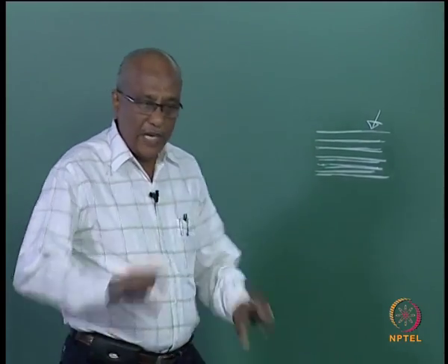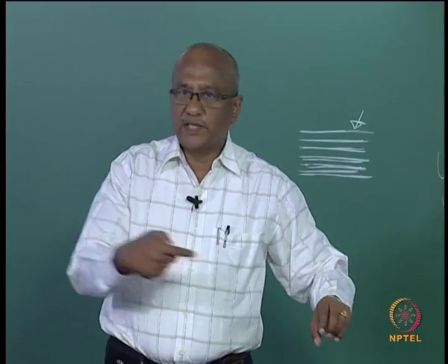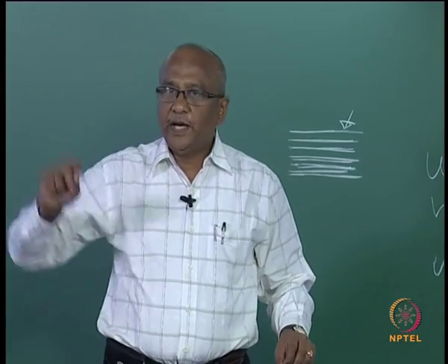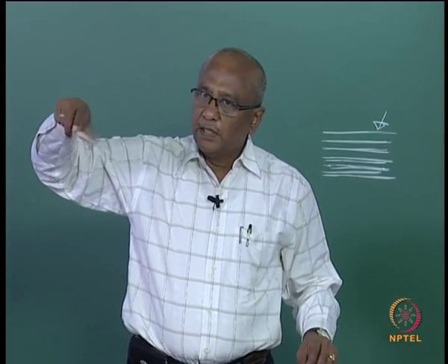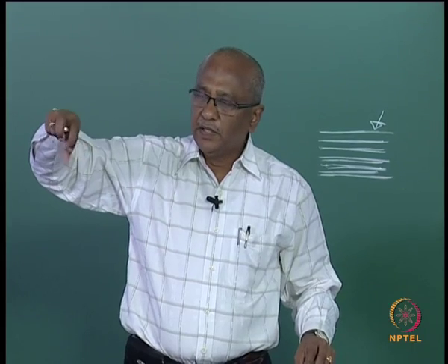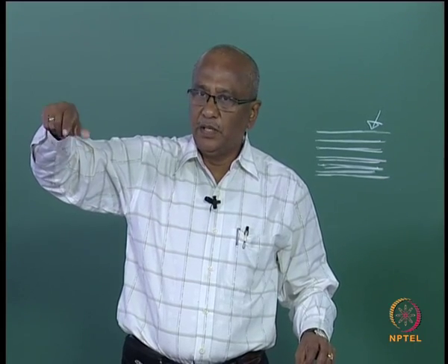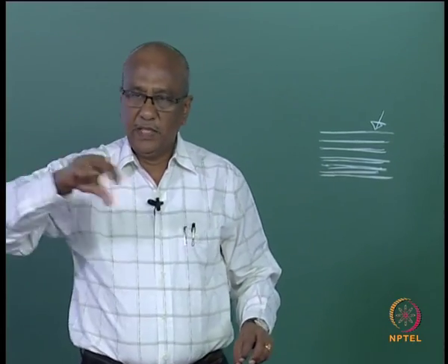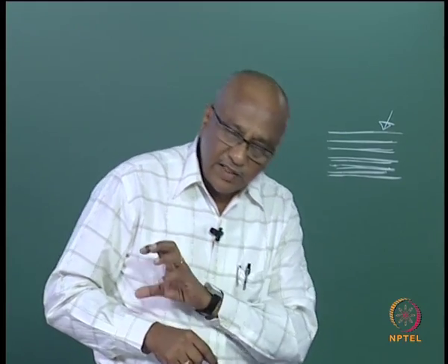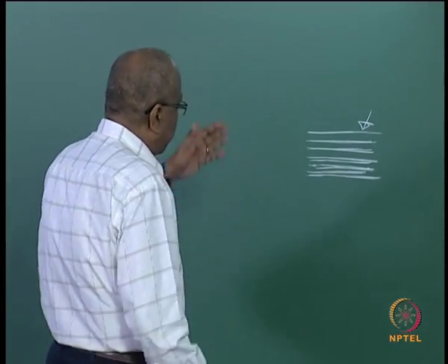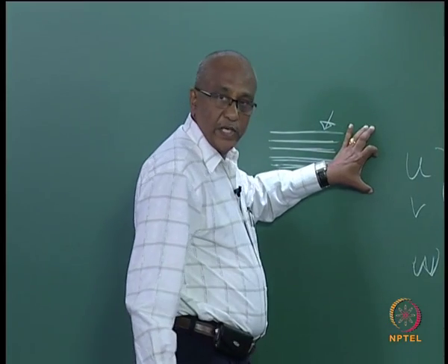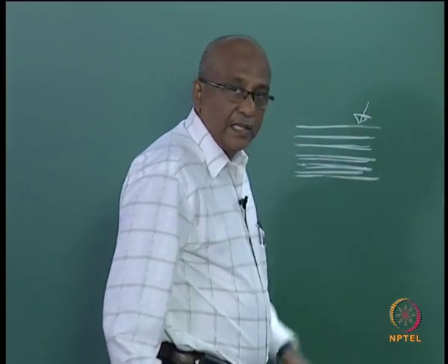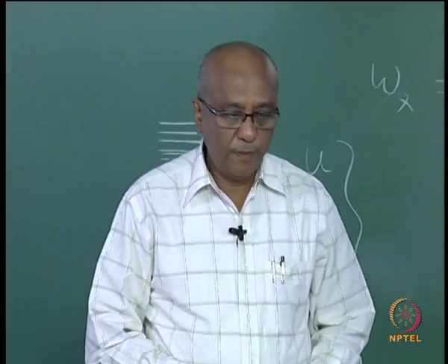So what do you do? You have a tube and you inject some dye so that you can see the path, and you control your Reynolds apparatus. This is what I am trying to explain. You can control your discharge, and if the discharge is very less and you control it in such a way that you can easily visualize the flow that is moving, you can generate a kind of laminar flow.